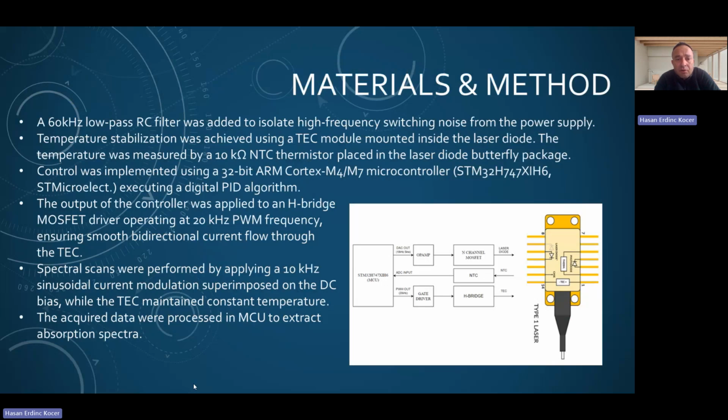The output of the controller was applied to an H-bridge MOSFET driver operating at 20 kHz PWM frequency, and spectral scans were performed by applying 10 kHz sinusoidal current modulation superimposed on the DC bias. The TEC maintained constant temperature. The acquired data were processed in a microcontroller unit to extract the absorption spectra.